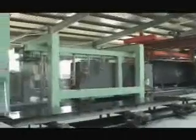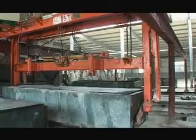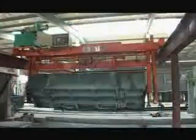4. Demolding, cutting and grouping. There are 2 types of cutting. One is air turnover and the other is ground turnover. For the air turnover cutting, when the hardness of the cake is ready for cutting, the mold is moved to the cutting process by an overturn hoist and turned 90 degrees, and put on the cutting pallet.